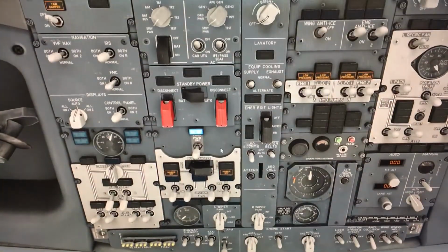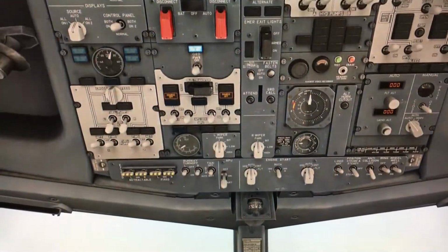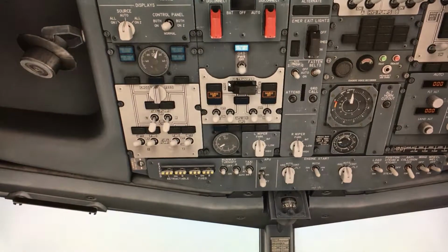Once the APU runs to good speed, we look at the power bus transfer unit, which is the switch box for the airplane. Now we're using the battery, and once the auxiliary power unit is ready, this light will come on. You can see there are 2 circuits for doing the power switch, which is for redundancy. So you have one actually working, and if that one breaks, the other one still powers the whole airplane.